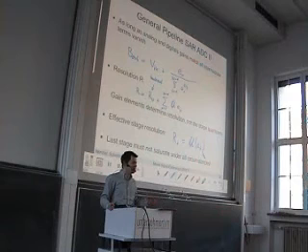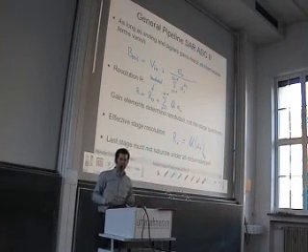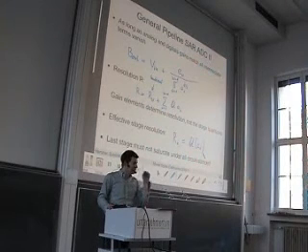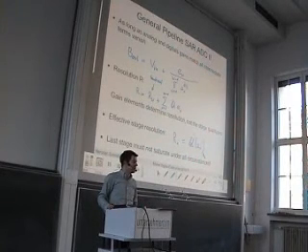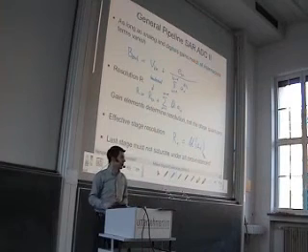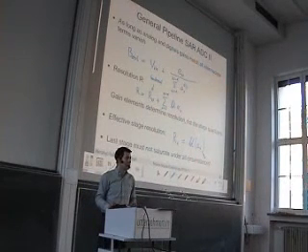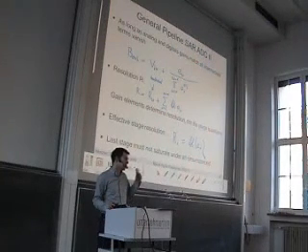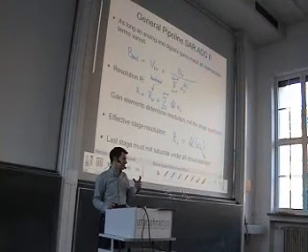You can cite me and say, okay, he said everything has some variation, so also the gain has some variation. If we implement the digital gain, it is fixed. So we run into trouble here, because then the intermediate terms do not vanish. What we can do is that we try to measure the analog gain.